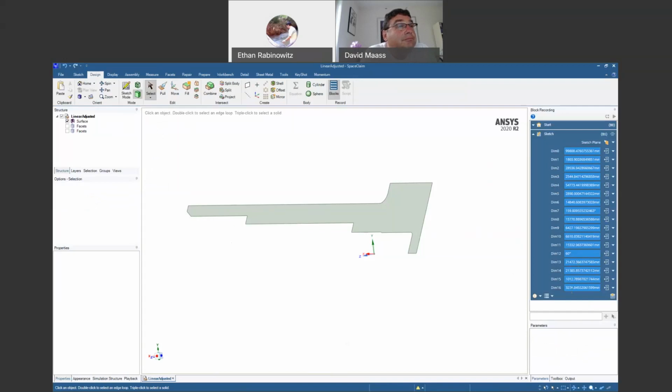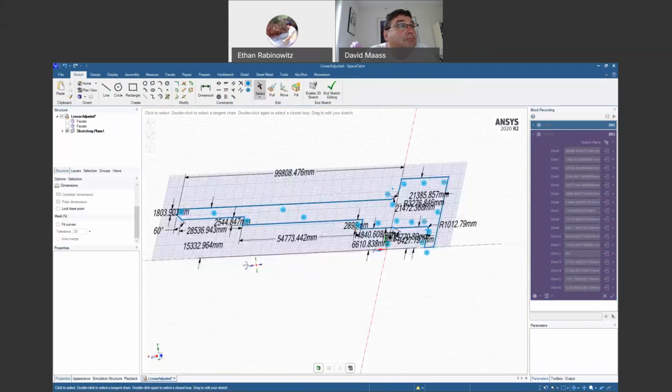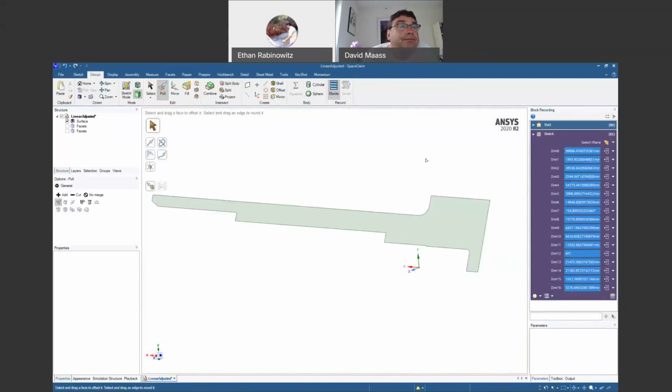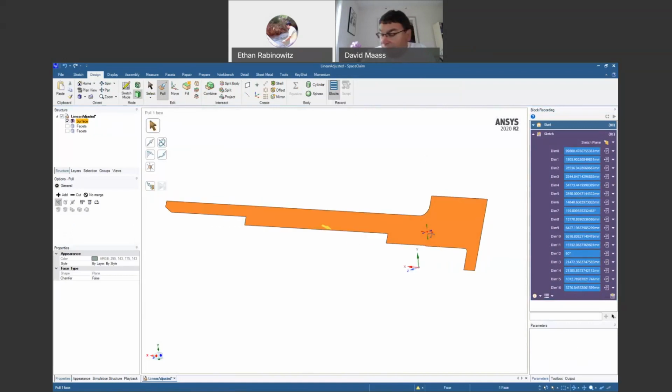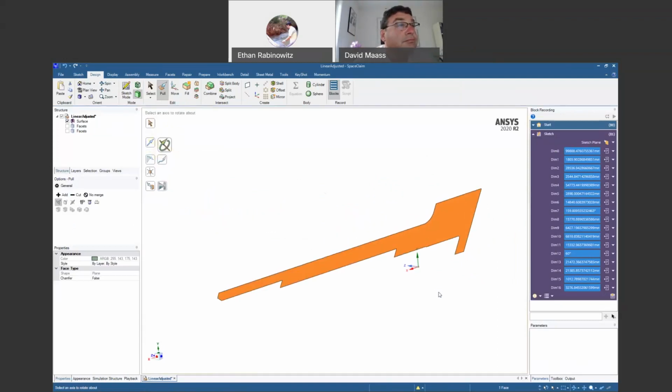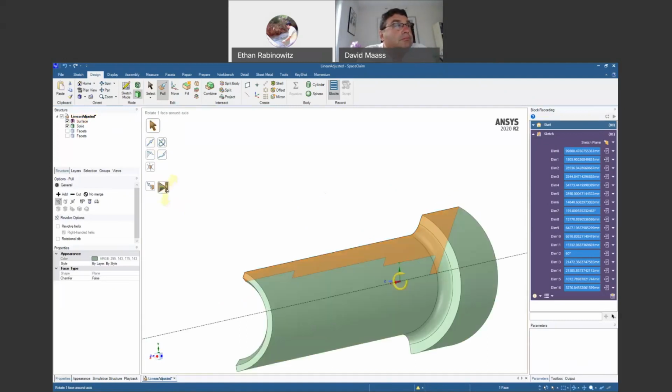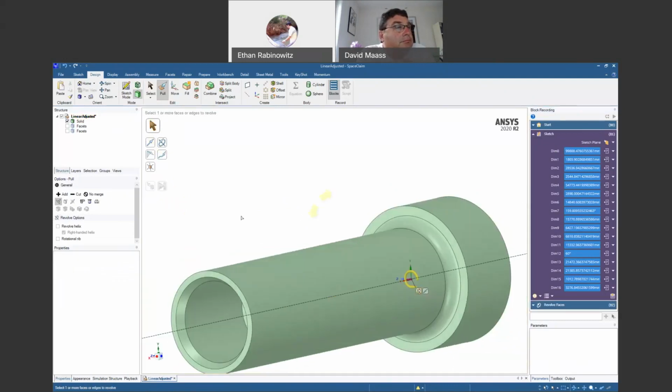But right now, if you have one sketch with a ton of dimensions and you want to edit them, usually the best thing to do is to go into the sketch and edit them from there. It's just a lot easier to know what's what in terms of updating. Understood. All right, so we've got this profile and we want to revolve it. The pull tool does our revolving. The pull tool does our extruding if we just pull it in a direction. But we can either use one of these modifying buttons or the keyboard shortcut Alt to pick an axis. In this case, the axis could be X. It could also be this edge because the edge is on X. So either of them are acceptable. And I can either hit Enter or click this play button or drag it around. And now we have that first body there.